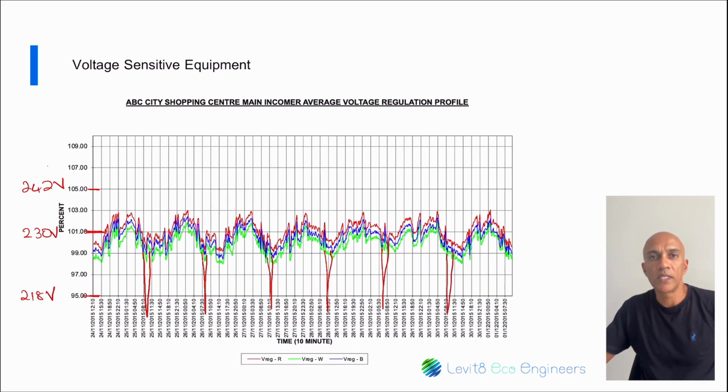So setting of limits and times will require you to do your homework beforehand, knowing the capabilities of your equipment. The time of the recorded trigger event will also give you a good indication of what happened at the time the trigger occurred. You could ask your client what specific operation took place when the anomaly is triggered, and this helps in pointing to the possible causes.